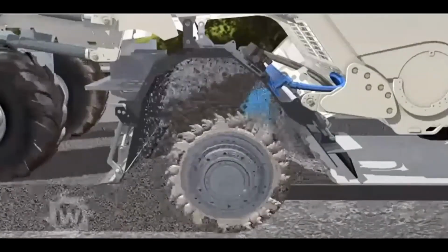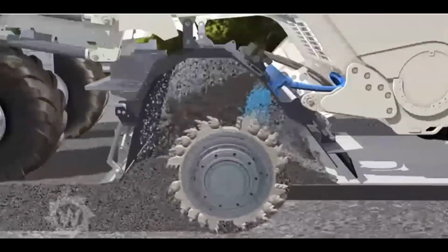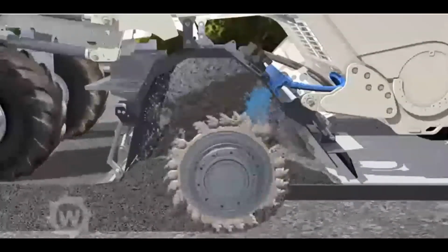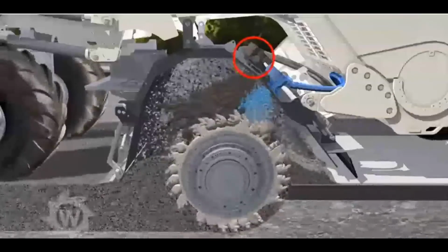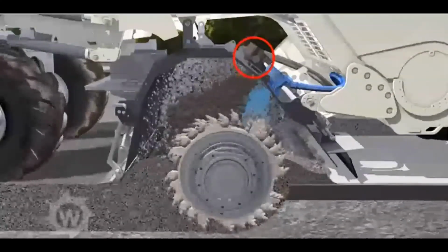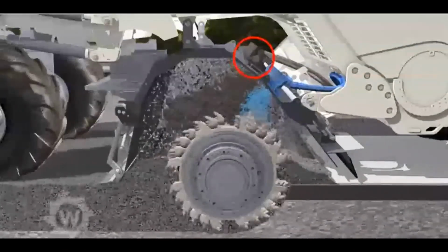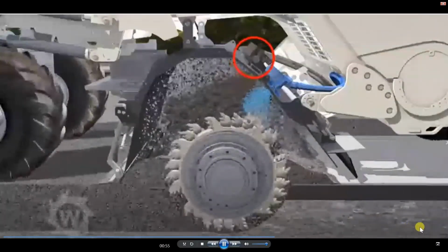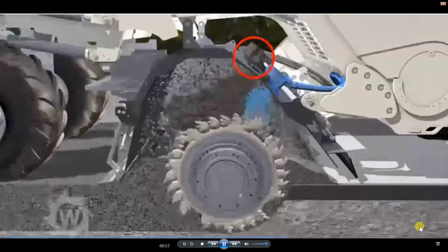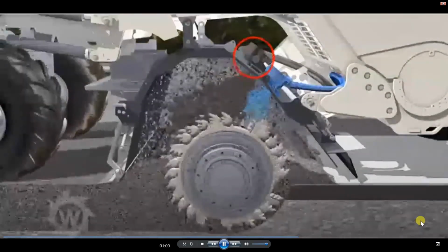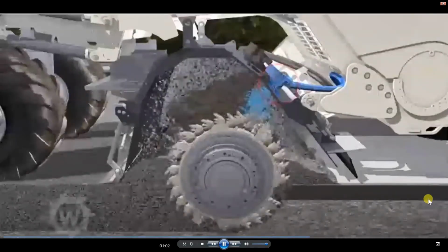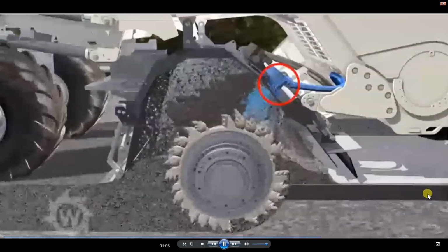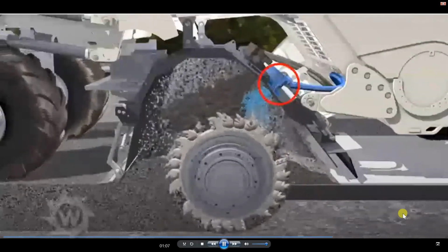As the recycler pushes, the powerful milling and mixing rotor granulates the damaged pavement layers. The pre-spread cement is mixed in at the same time. A special injection bar with expansion chambers produces the foamed bitumen and sprays it in. Water added to the process causes the bitumen to foam abruptly, expanding it to many times its original volume and distributing it evenly in the mineral aggregate mix. At the same time, the amount of water required for the mixing process is added via a second injection bar.